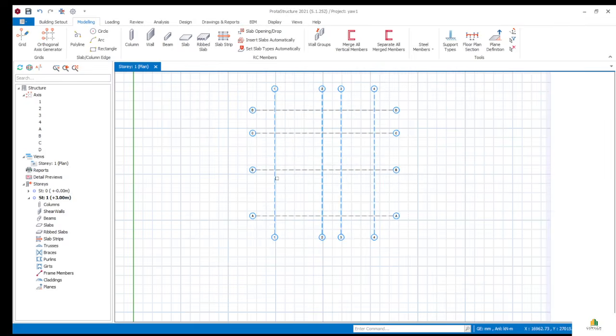So this is the direction 1 that I was talking about. The horizontal one, the direction 1, the axis label is A, and the step is 1. So from A, B, C, D. Then the direction 2, which is the vertical one, is step 1: 1, 2, 3, 4.